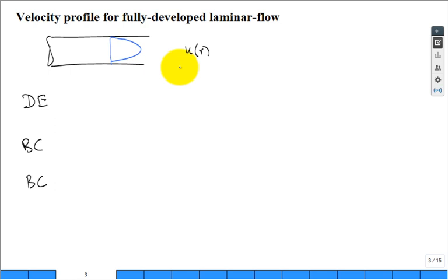What would be our governing differential equation? Well, for a little chunk of fluid like this in there, you do a balance. Now, it's not accelerating or decelerating, so I don't have any change in the linear momentum flow rate in or out of that little control volume written right there. It's basically what flows in, flows out. So there's no change in the linear momentum flow rate. But there are things which tend to balance each other. You have viscous shear forces acting, as well as the normal pressure forces acting on that little control volume.